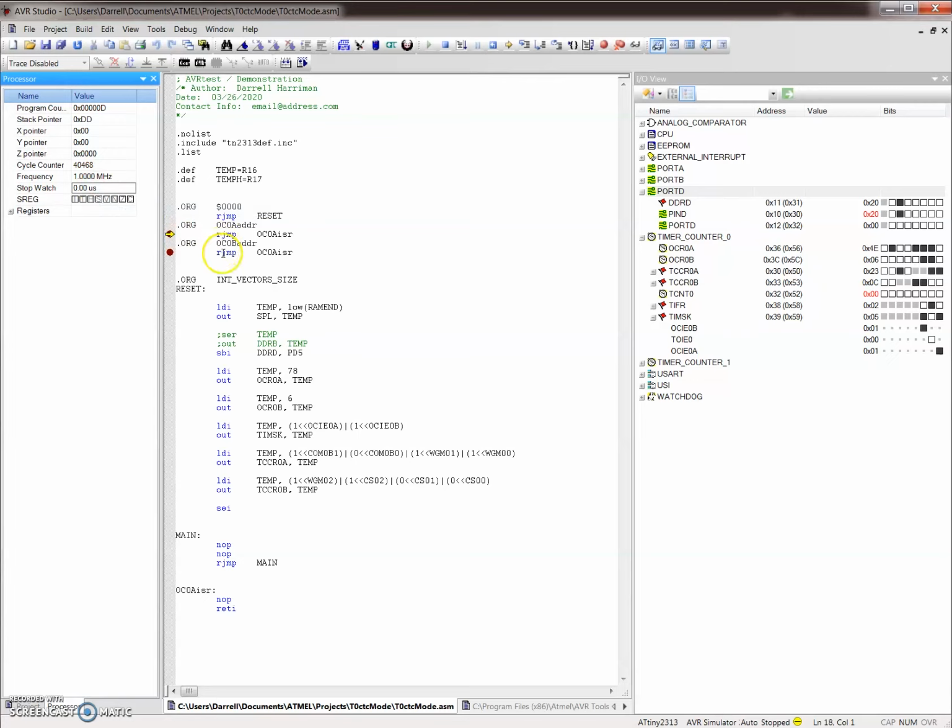And I want it to take approximately 1500 microseconds to get to OCR0B. So we run it, and we're at 1792. So that's 292 microseconds longer than we want. So again, if we subtract 1 from our OCR0B register, that means it's going to count 256 microseconds less time, because it's 256 microseconds per count, right? So that'll put us a lot closer to 1500 microseconds.